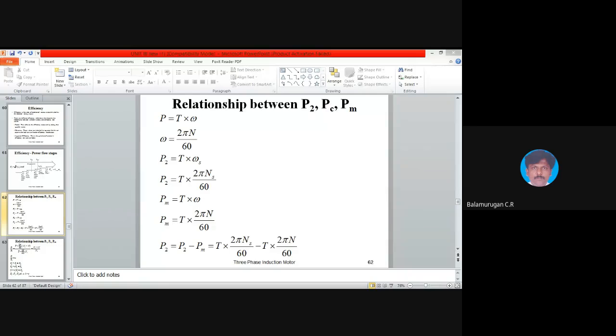No frictional loss. So efficiency, I already told. If you are having a motor, generator and transformer, what is the range of efficiency? In the first class itself I have given the value. Instead of frictional losses we can say no mechanical loss. The transformer does not have any rotating part, so mechanical loss is absent. So you will get the maximum efficiency compared to generator and motor.